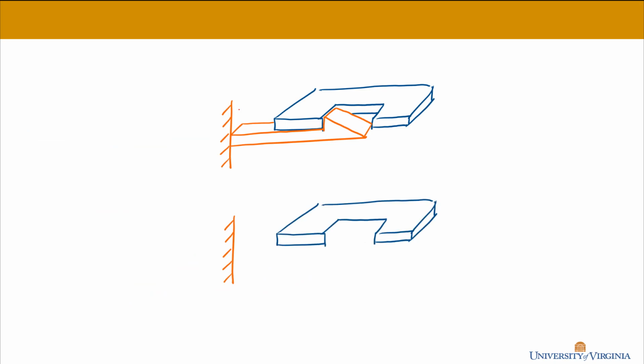So with that in mind, you could consider other kinds of shapes, like a softer shape, something a little bit more like this, that could allow the part to not only be easy to snap in, but just by pulling back on the orange part, it would have more of a curved surface that could deflect and be pulled out. And it's just a matter of understanding what your snap is for. Is it for a permanent connection, or is it for a connection that you need to be able to put in and pull back out, left and right on this drawing of the snap?